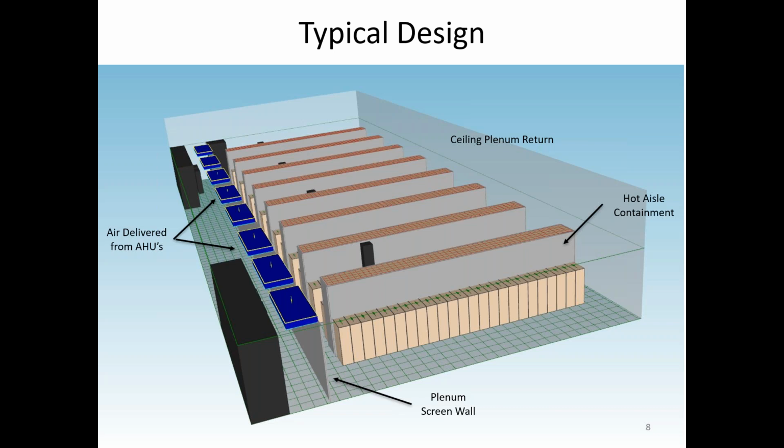It also makes the room cooler. One of the problems with cold aisle containment is the room becomes the hot aisle. It gets very, very hot. People don't like it. They go in and start turning down the thermostats, which make the air handlers work even harder and don't realize they're standing in the hot aisle. So we're going to be analyzing this one today.